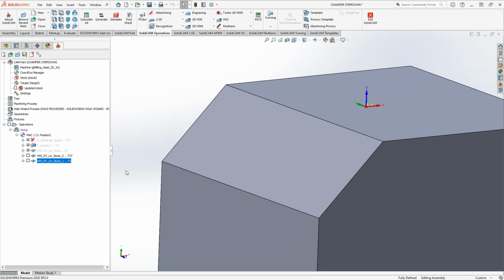I'm not sure what you mean by the RZ, Brian. RZ, I guess, is like the height of the scallop in the Z direction. Okay, gotcha. Because you're talking about a scallop, so the RA is more of a metric of the surface quality, whereas I'm guessing RZ is the max valley to peak. Okay, yeah.